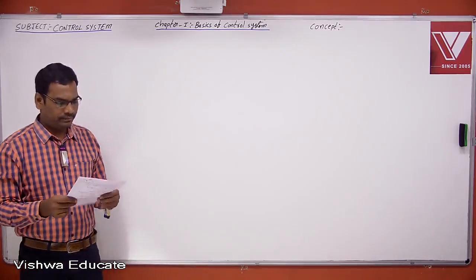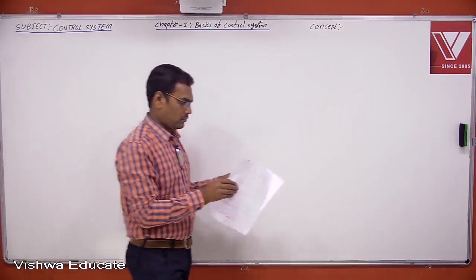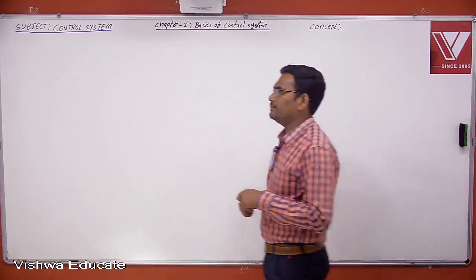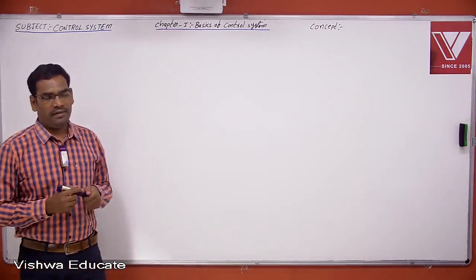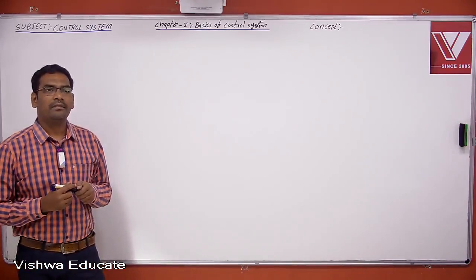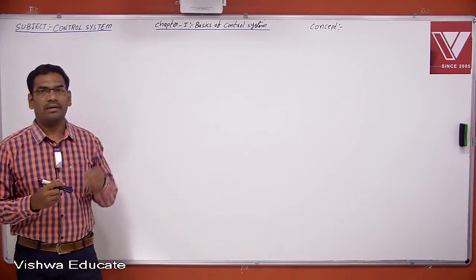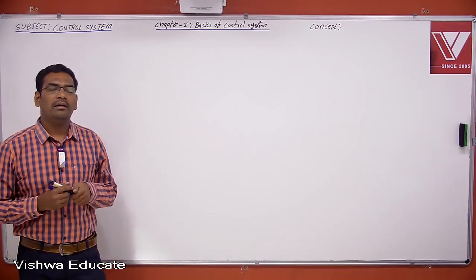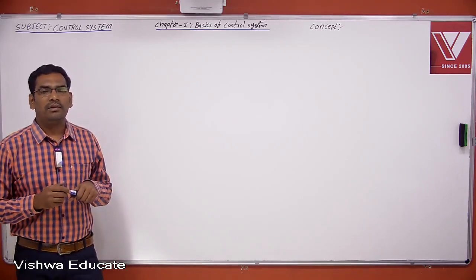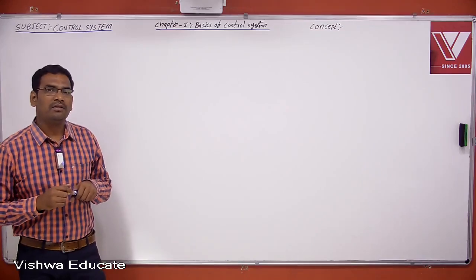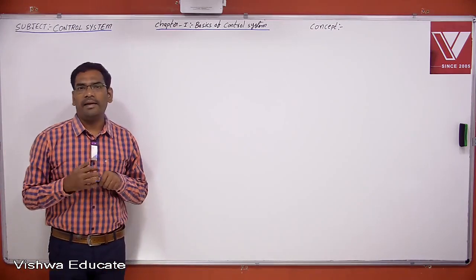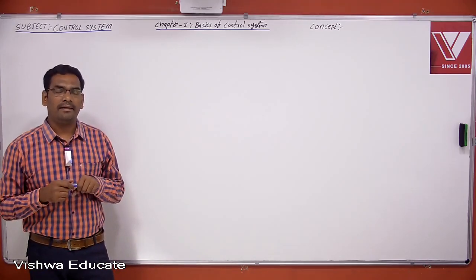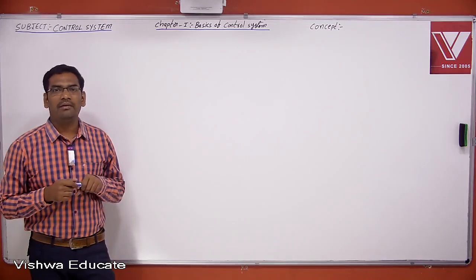Very good morning. In the last session, we finished the basics of the control system, open loop control system and closed loop control system, and its transfer function and its mathematical equivalent model. Based on those basics, we will find two important parameters. From the open loop transfer function, we will find the type. From the closed loop control system, we will find the order.